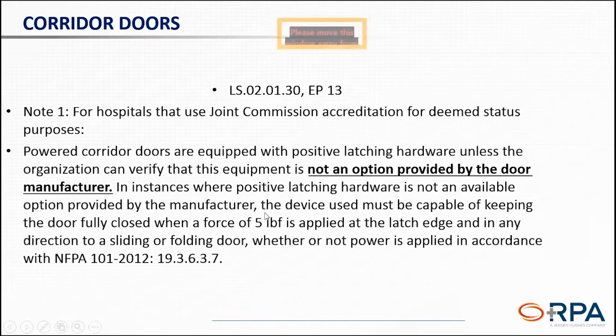We're seeing that a whole lot throughout the country, and that's putting people in a really hard position because typically those are doors to, say, an OR suite or perhaps a PACU where you're not typically opening the door manually. You're relying on the automatic opener to open it. So you're going to have to add some interconnects to the latching mechanism. You're going to have to add potentially interconnects to the fire alarm system. So it's a pretty costly fix.